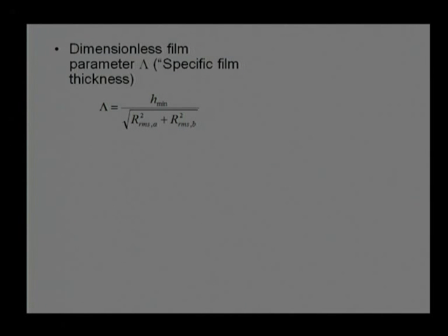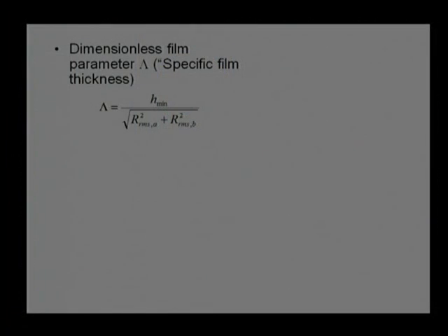To add some more value, to find whether solid mechanics should be used, fluid mechanics should be used, material science should be used, or chemistry should be used, or a combination of all four subjects should be used simultaneously, we can define one parameter that is known as the dimensionless film thickness parameter. It is a ratio between the separation between the two surfaces over the composite surface roughness.